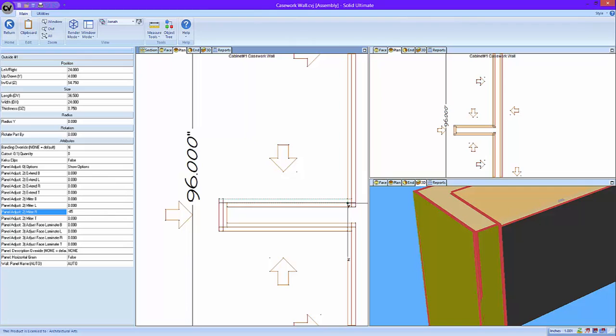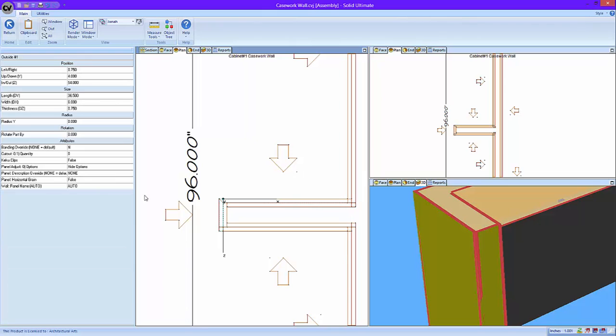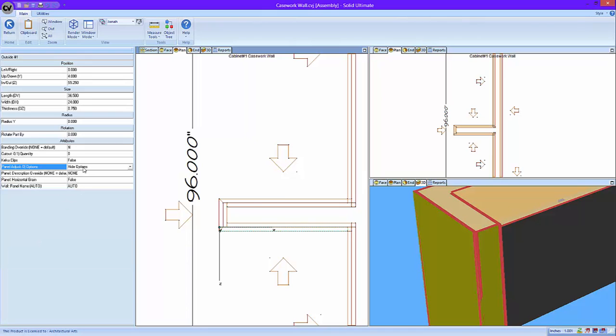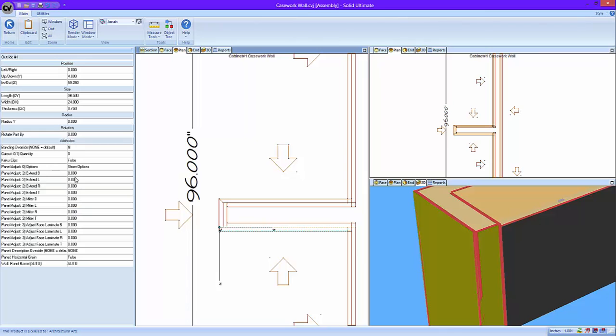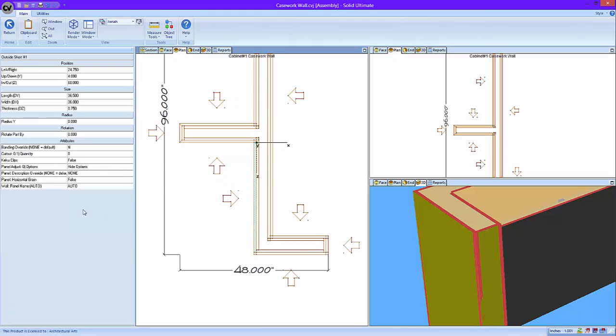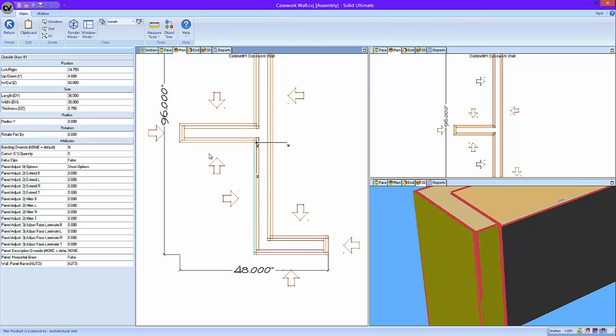So we're going to miter the right side of this face, and my UCS will in fact automatically add a 1/4 inch of oversize to any panel that's being mitered so that it can be placed back up on a saw and cut to length. It also helps because these walls generally grow a little bit and you don't want to cut your panels exact sized anyway. So if we didn't have mitered faces in here, we would want to go ahead and add some overage.